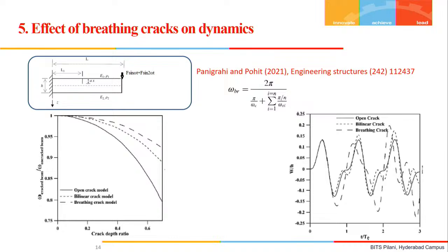So this is what I had to talk about, what we can take from it even if the crack is not growing. We assume that the engineering structure will not fail by cracking, but somehow if some crack gets developed, and we perform online condition monitoring, online vibration testing, so if we have the vibration data from the operating structure, by seeing the shift in the response, we can clearly identify where the crack is.